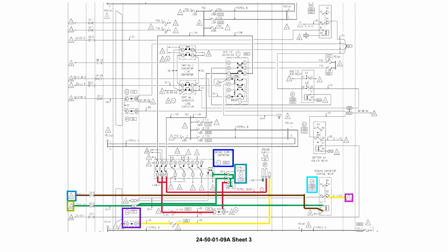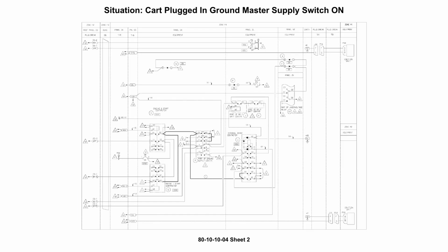With power and ground at the contact control relay, the contactor should actuate closed, allowing power waiting at pin Bravo 1 of the control relay to provide power to pin X1 of the ground supply contactor. Actuating the supply contactor closed allows power to flow through the contactor out of pin Alpha 1 to the PS1 bus bar, out of pin Charlie 1 to the PS2 bus bar, and out of pin Bravo 1 over to our next wiring print.